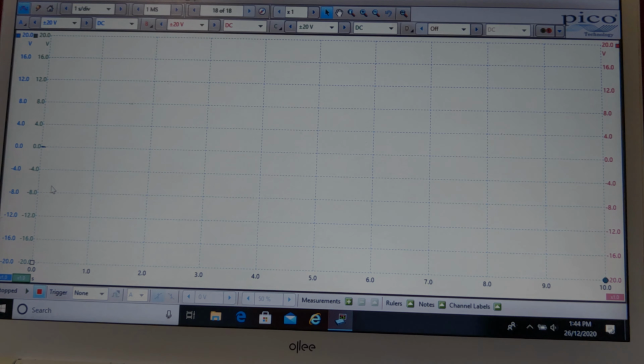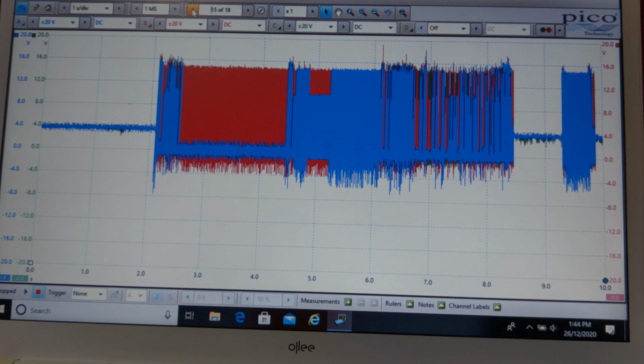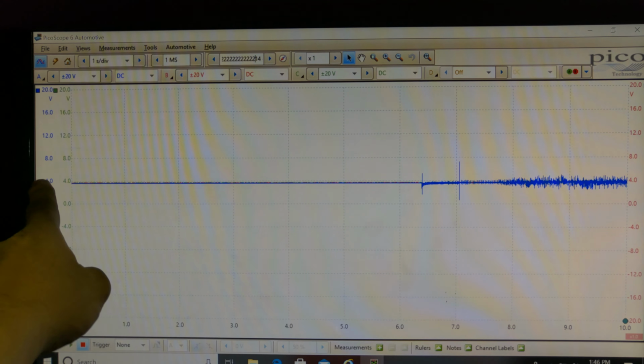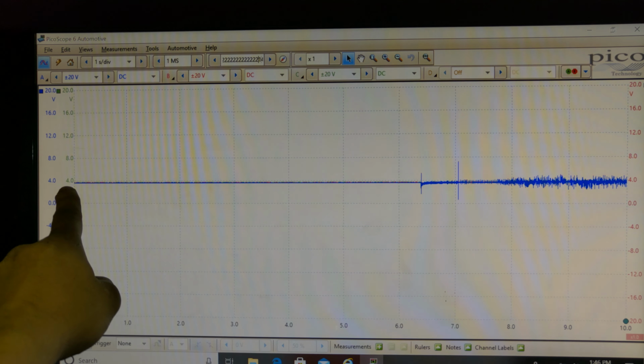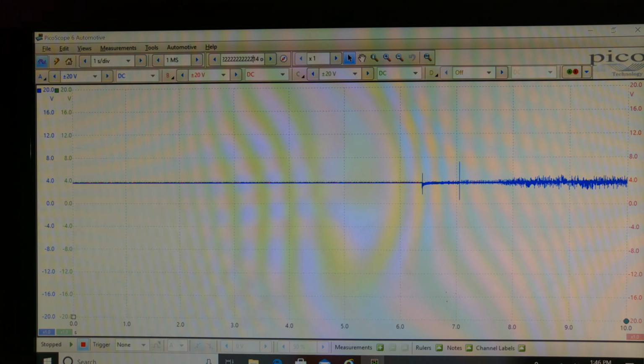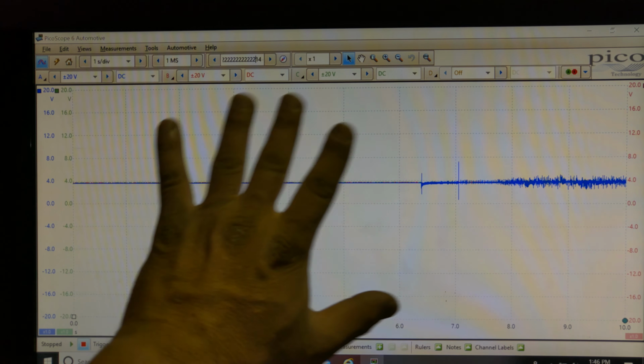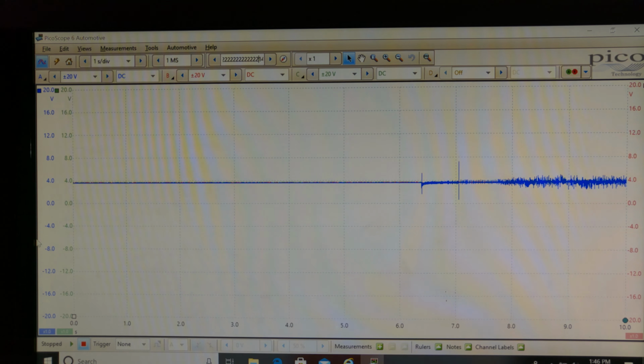Okay, I'll just try to explain what I'm seeing here. So I'm down on the actuator underneath the gearbox. There's one more at the top as well, like I explained to you. So let's go back to where we started. Basically, you see 4 volts on the green channel and 4 volts on the red channel. So all the channels are lined up there. They're on top of each other, so you can only see the blue trace, but all 3 are there, just believe me.